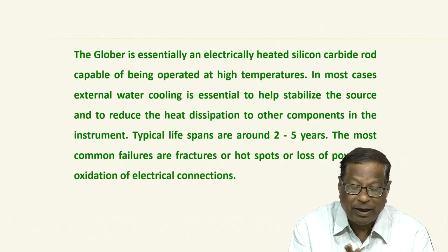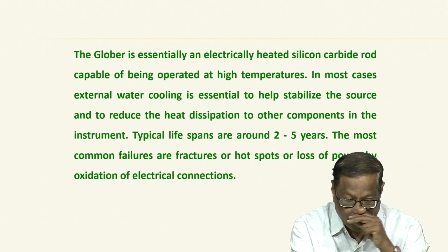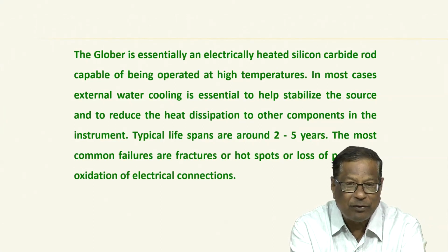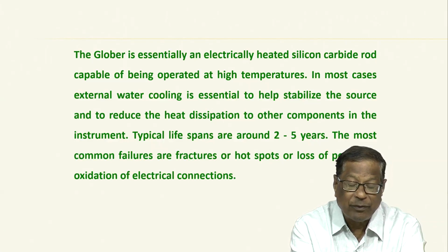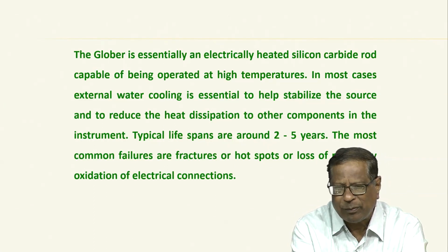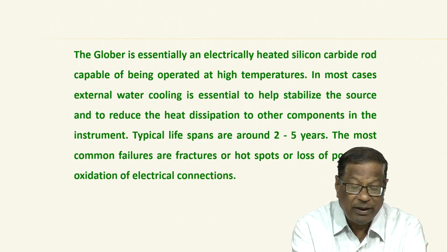It is essential to help stabilize the source and reduce the heat dissipation to other components in the instrument, because silicon carbide can be heated to very high temperature. So, the heat should not be passed on to other components of the instrument, which may melt, which may deform, and it may lead to shock, etc. So, heat dissipation has to be taken care of.